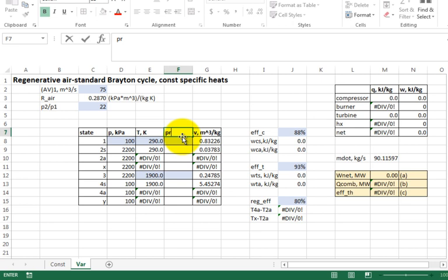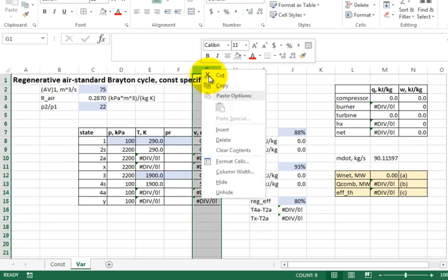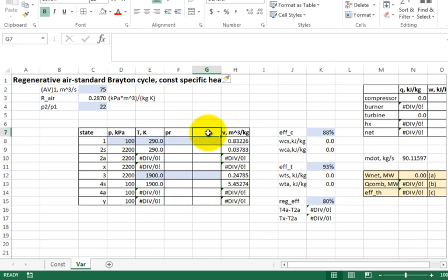What do you mean PR column? In table A22, do we not have VR and PR? But because the pressure ratios are given for the Brayton cycle, we're going to use the PR column. In the Otto and Diesel, our volume ratios were given. We used the VR column for isentropic conditions. All right, the other thing I need to put in is another insert, is I'm going to have my h's. Those enthalpies have to come out of table A22. So I'm going to have my h's in kilojoules per kilogram.